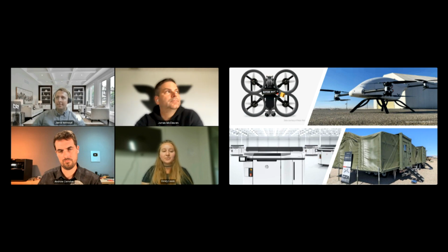Again, what we see is that strength-to-weight ratio is extremely important for UAVs. And this is a technology where we've been able to get extremely thin walls and really reduce the amount of material required because of the strength of those parts. The other thing I would say is people adopt MJF because it lowers the barrier to production, right? If you can have an idea, you can CAD it, you can send it to a service bureau and get one part made, and you can scale that all the way through production in the same material with the same process.